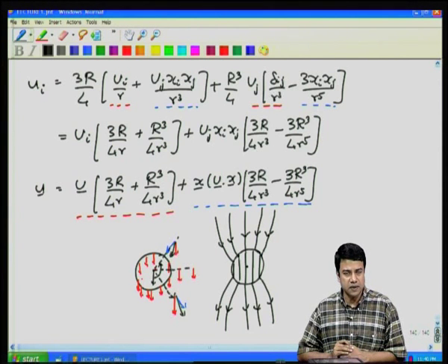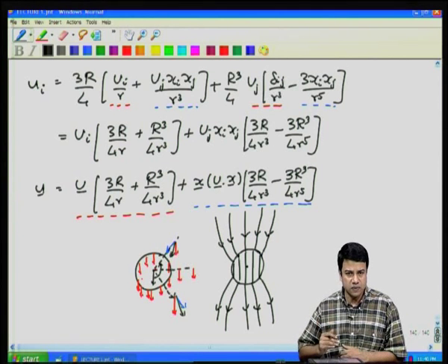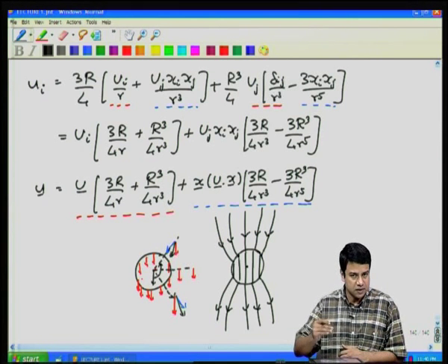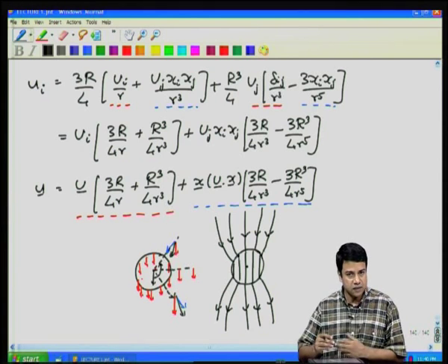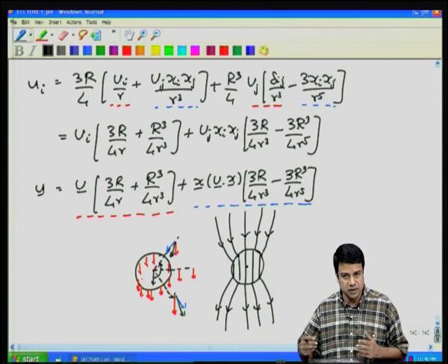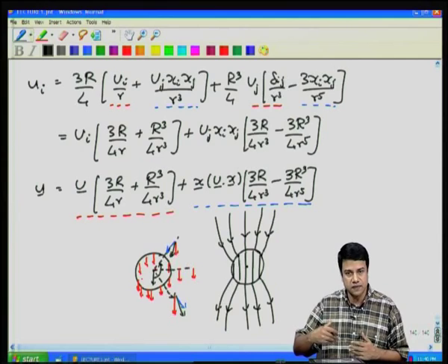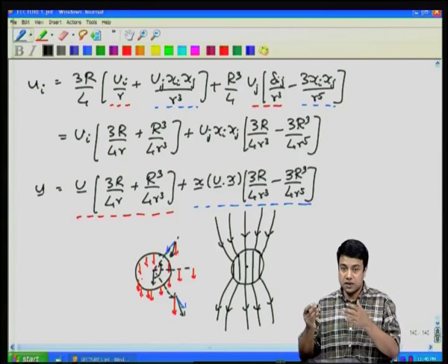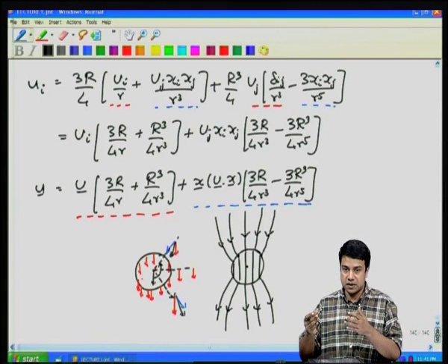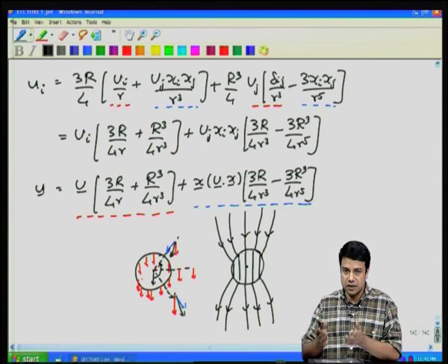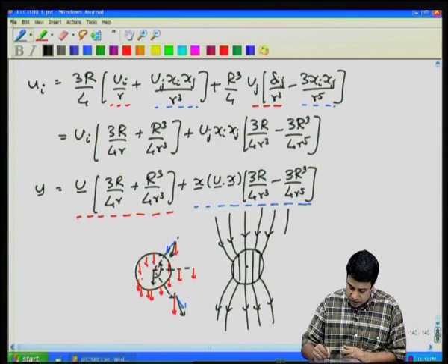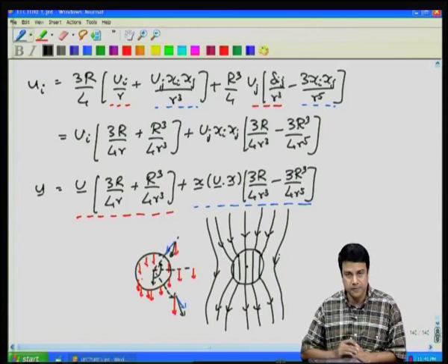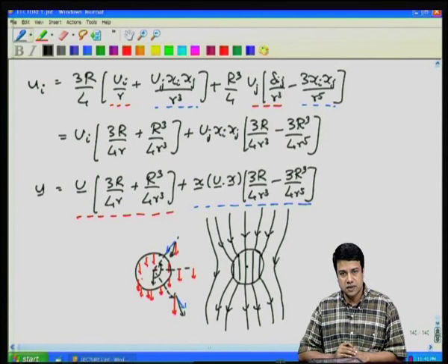It is sort of clear, because as the sphere is moving downwards, this is in a fixed reference frame. As the sphere is traveling downwards, the velocity upstream has to go outward, because it has to push fluid out of the way so that the sphere can settle. Velocity downstream has to come inwards, because the space that is vacated by the sphere as it moves down has to be occupied by fluid coming inwards. Okay. And if you look near the sphere, you will get something that goes like this. So, this is the kind of velocity profile that you get in a fixed reference frame.